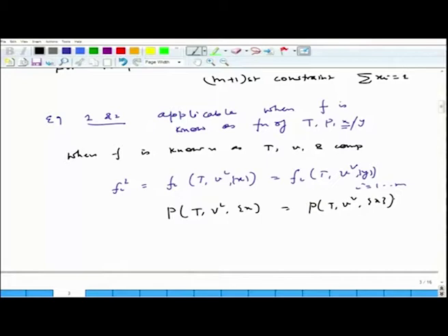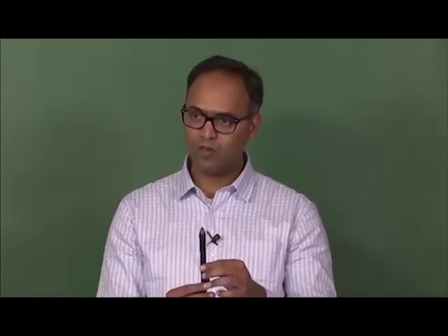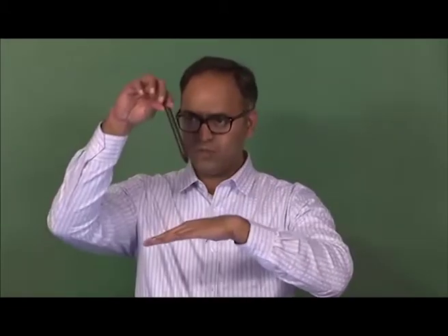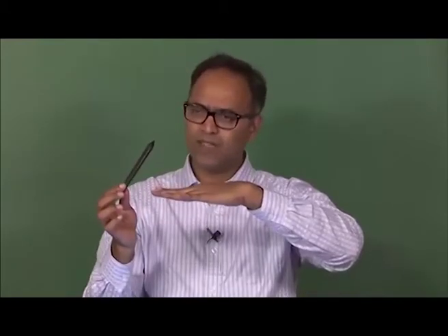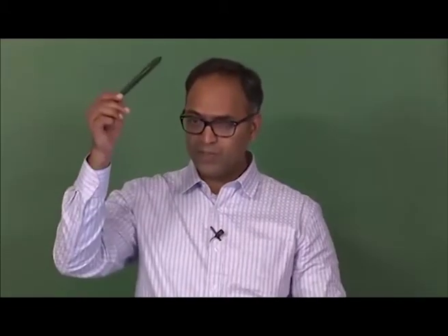Remember, pressure is basically a tensorial variable. So the trace of it, or the average value of the diagonal, would be the hydrostatic pressure, the pressure which is felt by a single phase. But at the interface only the normal component will be at equilibrium based on the force balance. Overall, the pressure felt by the vapor should be the same as this. This is a condition, assuming of course that there is no gravity effect. So pressure should be equivalent across the phases.